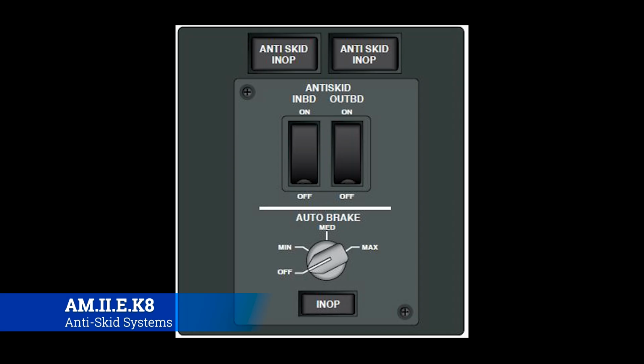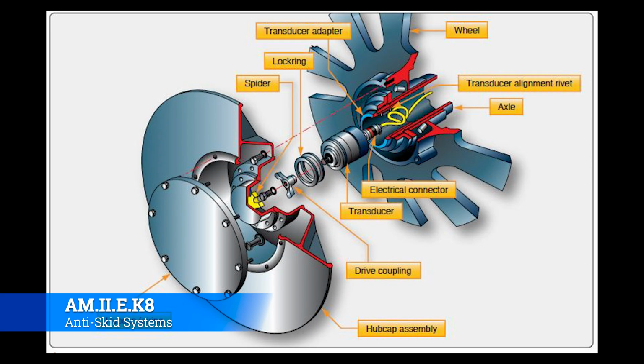We'll go over auto brake real quick, but essentially, whenever the aircraft lands, weight on gear comes on, and it knows we need to start applying the brakes, so it does it automatically, and you have the anti-skid locked on in case certain conditions are present that could cause a skid. So the airplane is actively looking for a skid while it auto brakes itself at the right time at the right rate.